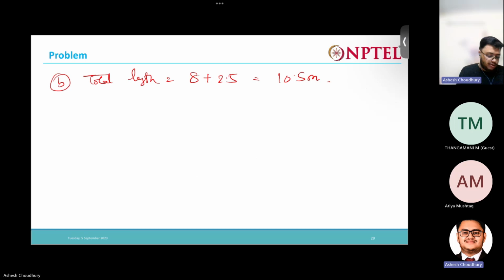Okay, 10.5 meter. Now, generally, for commercially available geotextiles, the width ranges from around 3 to 4.5 meter. In that case, what can we do? One option is to place it like this, perpendicular. The length will be like this, and the smaller direction will be like this. Obviously, we need to provide some seam or overlap along the out of plane direction.